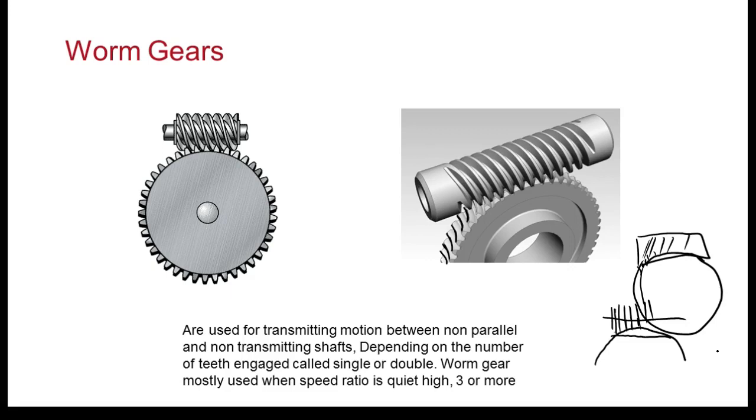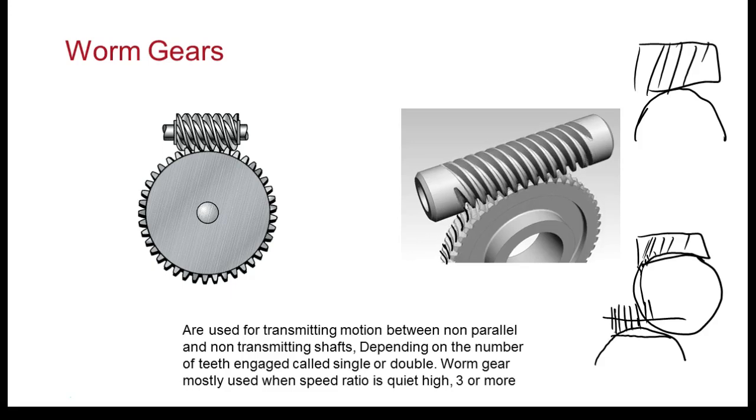So instead of coming in here and trying to make all the force be carried by just a couple of teeth, right? You understand? And we can actually see this on these worm gears over here. Usually the gears are grooved, and then the worm has a groove in it, so we can get as many teeth in contact between the two gears to transfer a higher torque. And these guys can transfer a lot of torque.